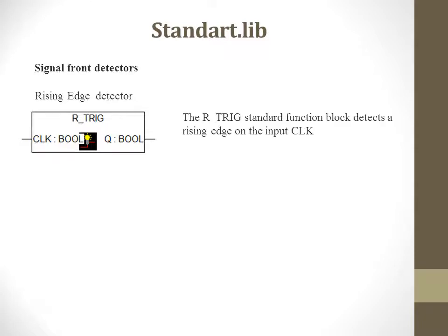It is called R_TRIG. The R_TRIG standard function block detects a rising edge on the input of this block.